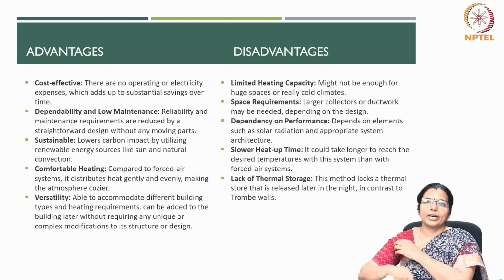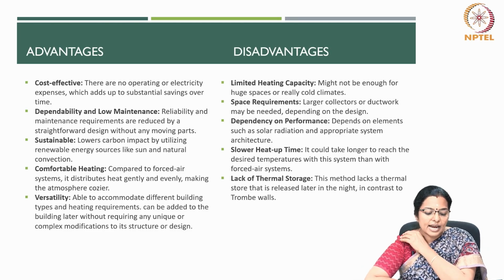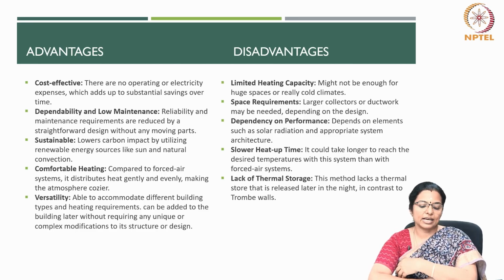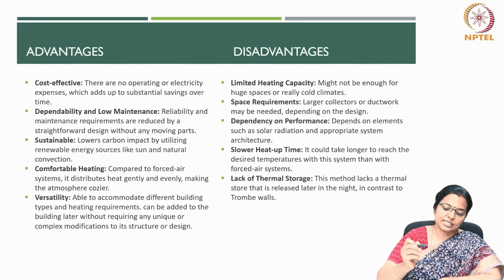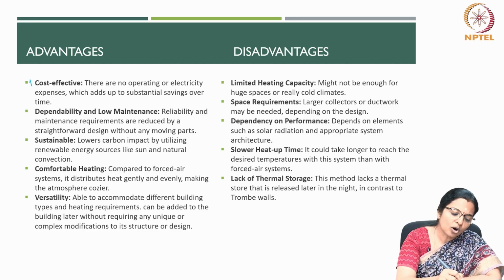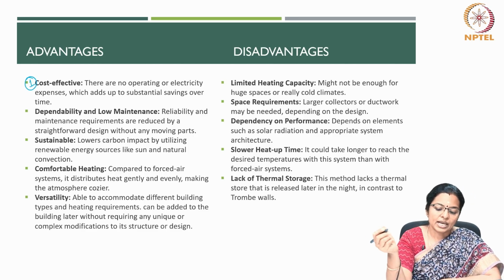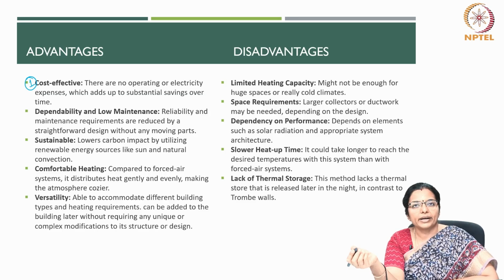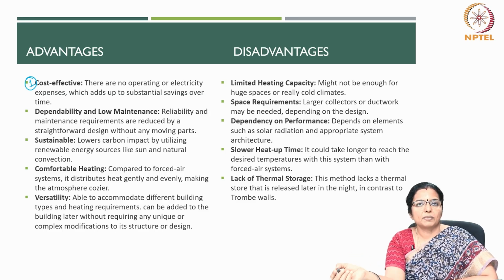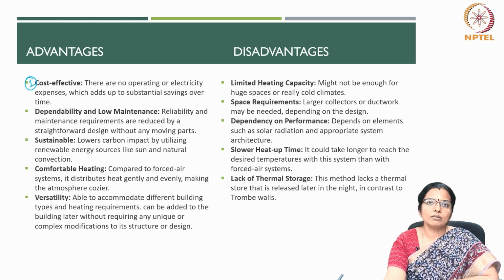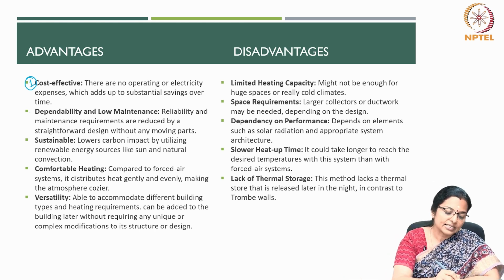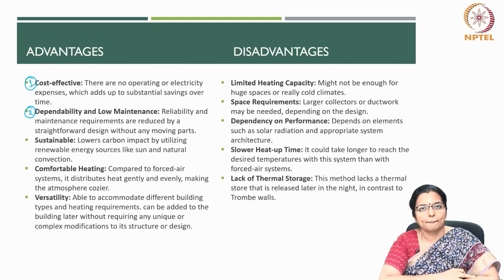Let us now look at the advantages and limitations of thermosiphons. First is cost effectiveness. There are no operating or electricity expenses, which adds up to substantial savings over a period of time. Second is dependability and low maintenance.